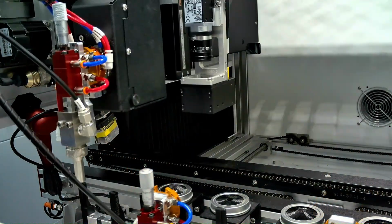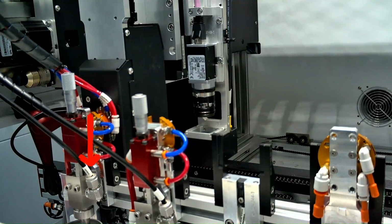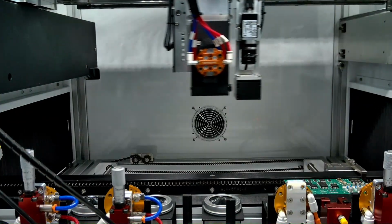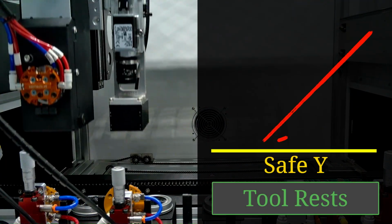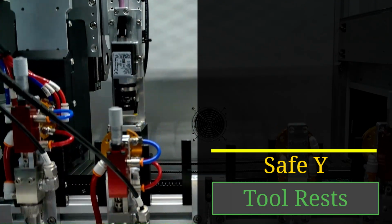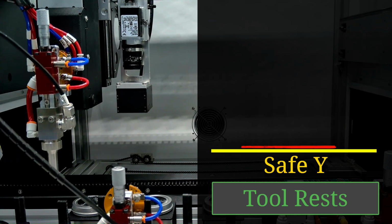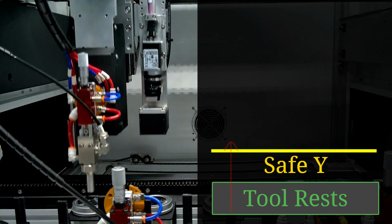The Z retraction property controls the approach distance above the drop location used when dropping off a tool. The safe Y plane is a point along the robot's Y-axis. This absolute point on the Y-axis is safe to move along with any of the tools installed. When changing tools, the robot moves to the X-coordinate from the tool rest's drop location and the safe Y plane before moving into position.